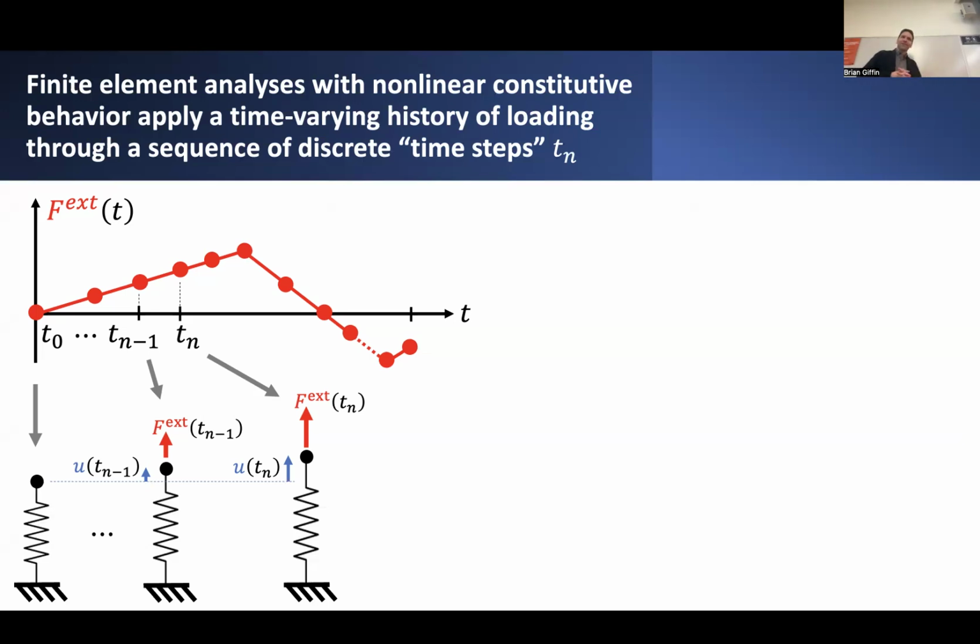And why do we want to do this? Why do we even care about cyclic behavior? Well, in general, if we were thinking of the structure as behaving in a strictly linear elastic sense, then it doesn't really matter whether we subject it to cyclic loads or whether we just consider the maximum load that the structure would be subjected to under those various cycles. Really, we only need to worry about cyclic loading if the behavior of the material is sensitive to the whole history of deformation that it has been subjected to.